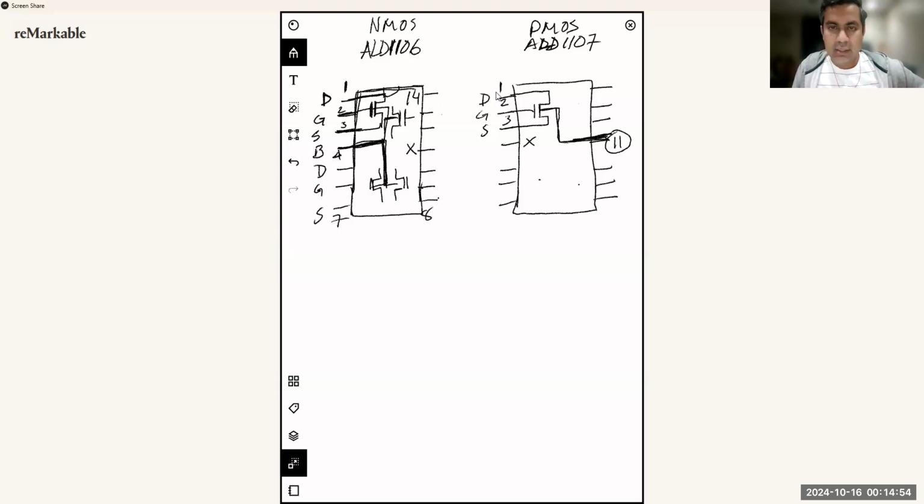Once you build this circuit, you only have one external component, which is a resistor, and then 2 sources that you're going to sweep. In simulation, you are just running this sweep analysis. And in the experiment, you're also doing that sweep manually and just recording the current through the ID terminal, the drain to source terminal. And once you do that, you can compare the values of the parameters. So that's about everything about this experiment.